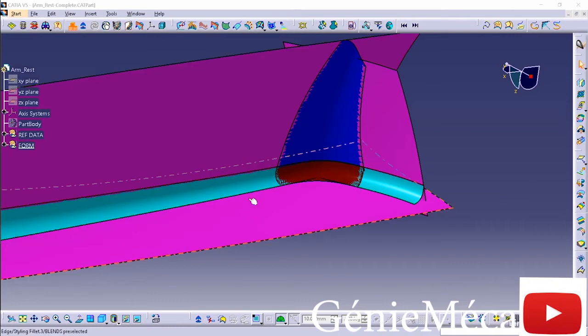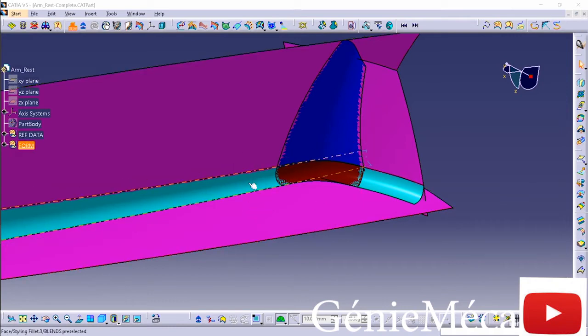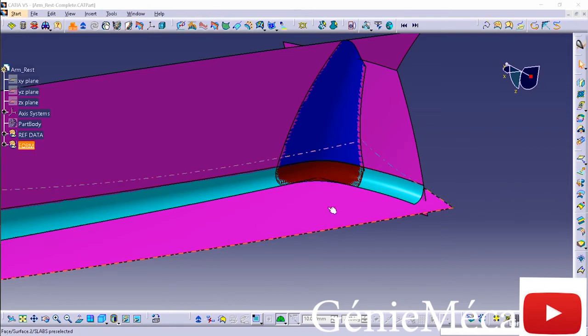So to connect these primary slabs, we put these secondary surfaces in, and oftentimes where secondaries and other primaries come together to form these little almost ball corners, they're called tertiary surfaces. These are typically the most mathematically complex because they are built off of blend surfaces, which they themselves are relatively complex. For every order of continuity that you require out of a surface, you have additional math that needs to be imparted on that surface.